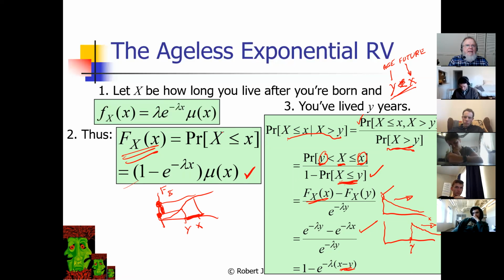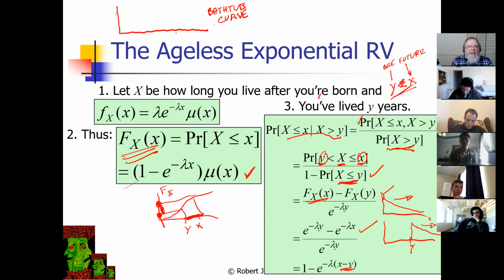And what happens is that there is this curve referred to as the bathtub curve. And you'll see why in a minute. And the bathtub curve goes flat for a long time. And this is a function of time. And during this constant period in the bathtub curve, your probability of living is exactly the same. But on one side is something called infant mortality. And you know why that is, because many times when babies are born, they don't live very long. And on the other side is old age.